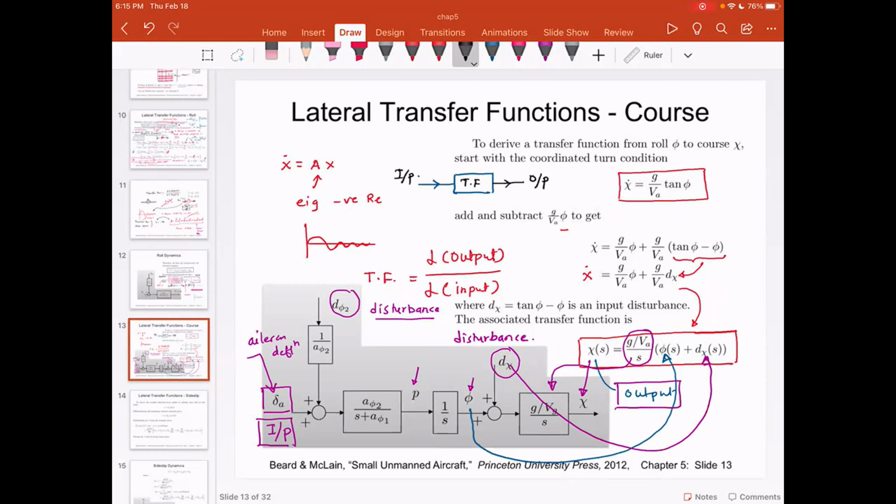And the objective of control is to identify this feedback or come up with some sort of a PID controller, some sort of a controller mechanism. In other words, add a block over here, which I'm going to call C. C can be used as a compensator or a controller. Use this controller block so that once you feed the error to this controller, it modifies the transfer function so that the system is stable.